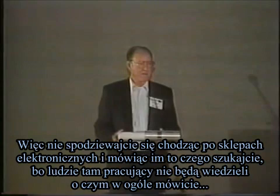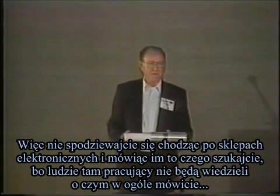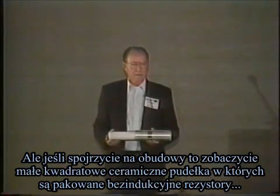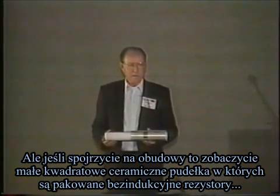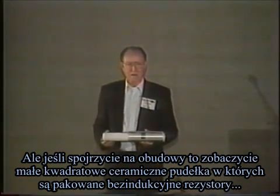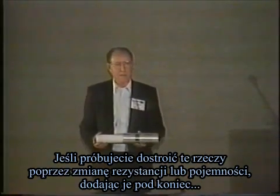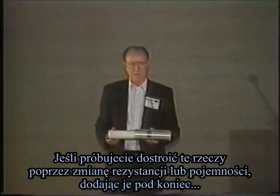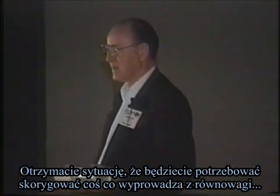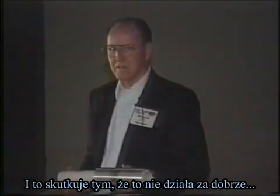So don't expect to walk into Radio Shack and tell them that that's what you want, because the people that work there won't know what you're talking about. But if you look on the packages, you'll see there's a little square, ceramic box-looking deal that says on the top of the package that it's a non-inductive resistor. Now, if you're trying to tune these things by changing the resistance or the capacitance and you're adding these things in, you get into a situation where every time you get one thing corrected, you've got something else out of balance. And the net result is it doesn't work very well.